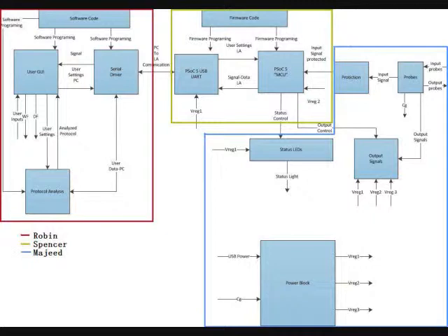In the output control block, we will be controlling our output voltage by the MCU. In the LED status plug, we will turn our LEDs on and off by the MCU, and it will show different light colors for reading, waiting, and power. The protection plug will show the physical connection. The purpose of the protection plug is to not allow more than 5 V DC to go into our PSOC and destroy it.